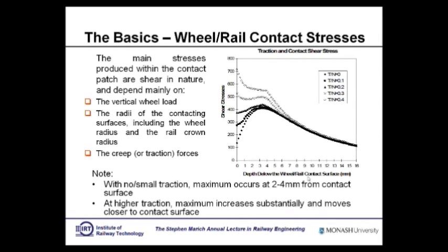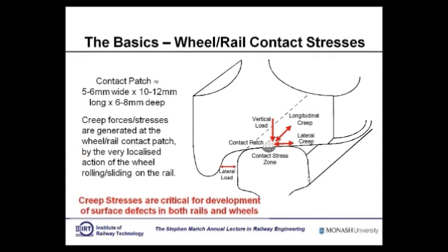Now, this is just on a sideway move. Anyone can sell high tractive effort locomotives, can't they? If you've got all these high traction locos, less money or whatever it is. High tractive effort, high traction. So no one among the locomotive manufacturers actually mentions the destruction that each high tractive effort locomotive does to the track, to the rails and wheels, and the track, of course, and so on. But I can save you a couple of $1 million because you're not going to require so many locomotives.